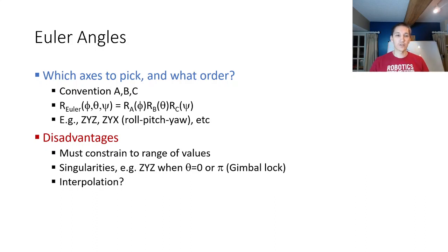There's actually a redundant representation here of any rotation that doesn't have a pitch associated with it. The same thing goes for roll, pitch, yaw angles. If I were to pitch by 90 degrees, either plus or minus, essentially if I think about an aircraft pointing vertically upwards, then I can roll. The rolling is the same thing as yawing in that case.